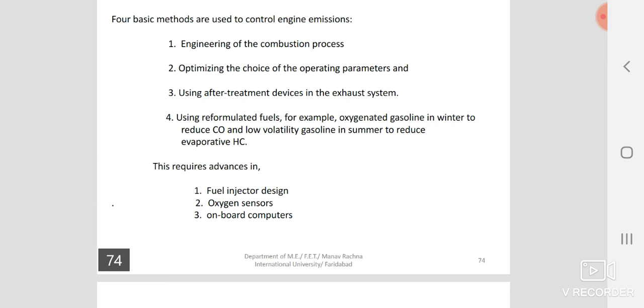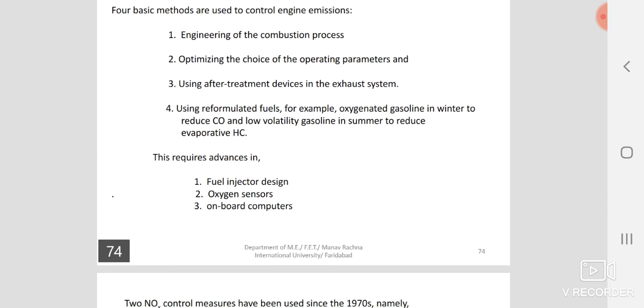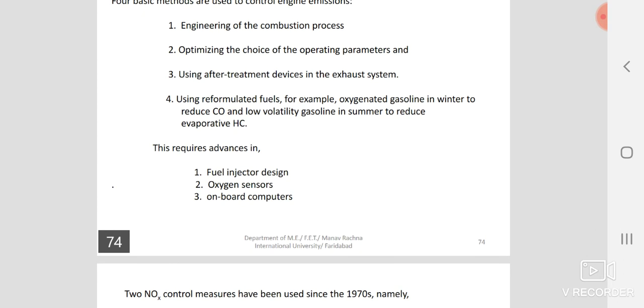This can be placed in a central location so that the total combustion happens. Similarly, the fuel injector in case of CI engine can be placed in central places so that the fuel doesn't have to travel a much distance or to a corner of the cylinder where the chance of knocking is more. Because in case of diesel engine, the unburnt gases produce knocking.